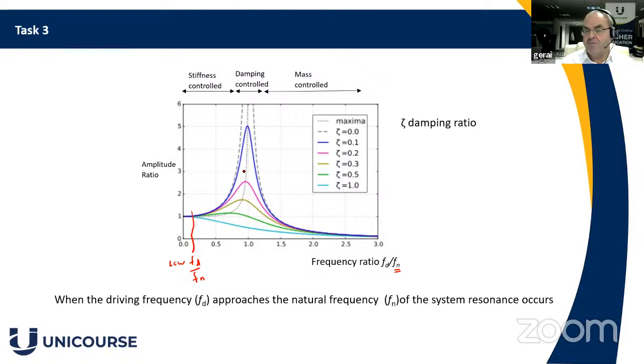And it's true, it does happen. If you know anybody who's been on board a ship, you'll see there's a notice on the maneuvering panel of a ship's engine. There's a barring speed to avoid resonance of the propeller shaft. You have to increase the speed of the engine quickly across this resonant zone and move into this part here to operate normally, to avoid the resonance occurring. So it's a real thing. It does happen.